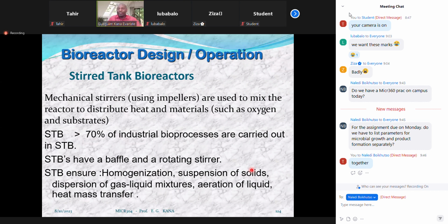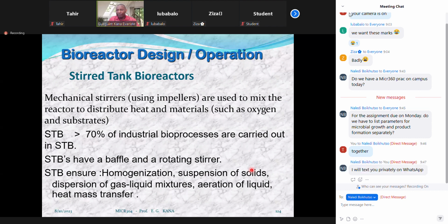But basically, for the raw material, you're going to have a medium that will provide a source of nitrogen, a source of carbon, a source of some amino acids needed, sometimes vitamins and mineral salts. The entire composition will have to undergo sterilization, and you need to have those ingredients in the right proportion. Especially for industrial, large-scale processes, they may not go for pure glucose, but for some waste like sugarcane molasses. That does not exclude the fact that they need to provide an additional source of nitrogen, vitamins, and other ingredients.